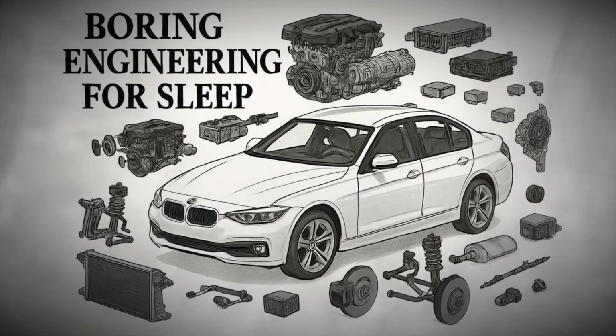The engine also requires several subsystems to function correctly. The intake system brings in air, sometimes compressing it with a turbocharger or supercharger to increase power. The fuel system delivers gasoline or diesel in carefully measured amounts, often using modern fuel injection for precision. The ignition system uses spark plugs in gasoline engines to ignite the fuel mixture, while diesel engines rely on compression alone to ignite the fuel.